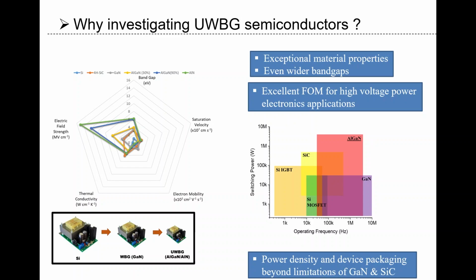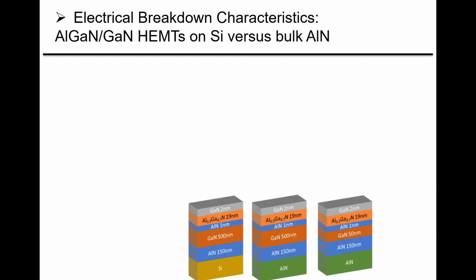This is long-term exploratory material, so it's pure research so far, which is less the case for vertical, which is happening on GaN bulk, and also now on GaN on silicon with what we are doing. So the interest of aluminum nitride is an even wider bandgap and an even larger electric field strength. I'll just go very quickly here, just to show you the interest of the aluminum nitride platform.